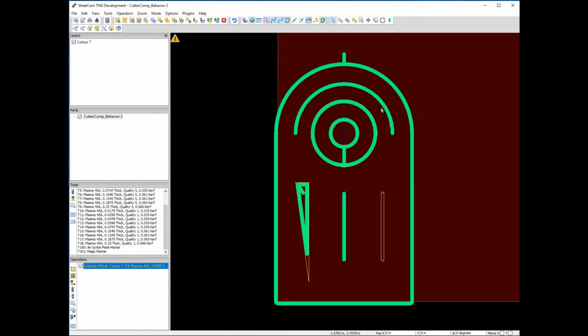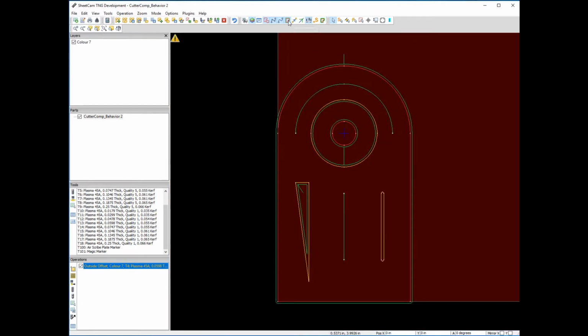And what I did in this drawing, let's turn off show true width and show toolpaths. I created this slot 40 thousandths of an inch wide to illustrate that it can't be cut, because our kerf over here is 55 thousandths of an inch wide, so we simply cannot cut it. And in a minute here, I'll show you your two possible solutions to this problem. But right now, let's go back to our cutter.